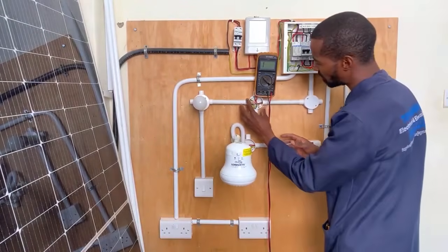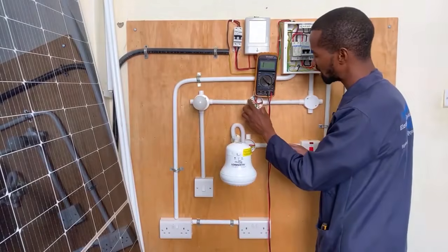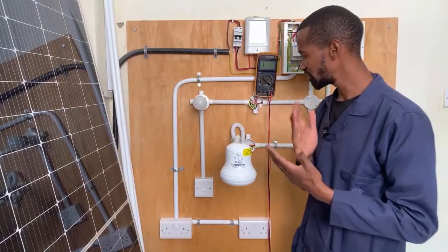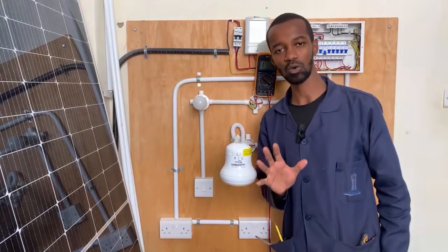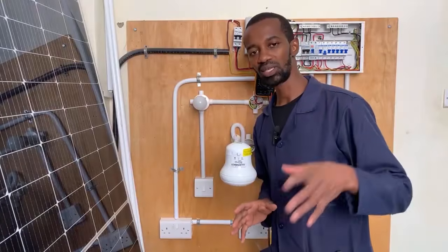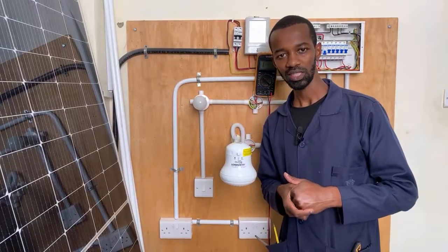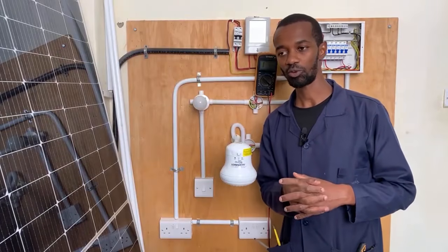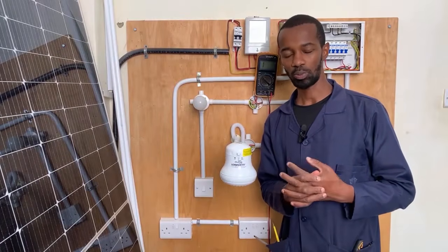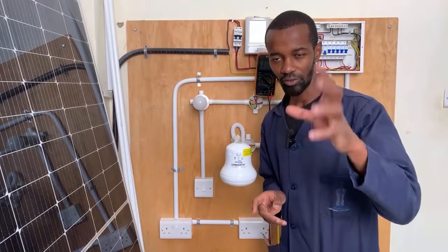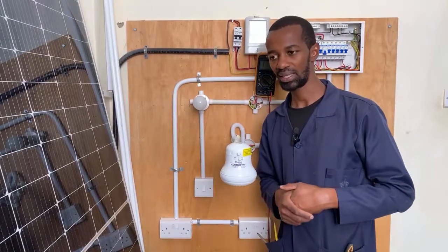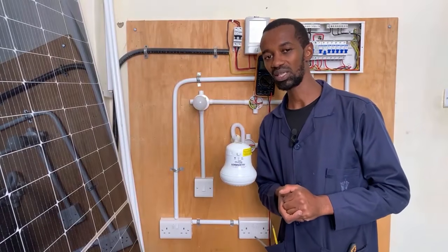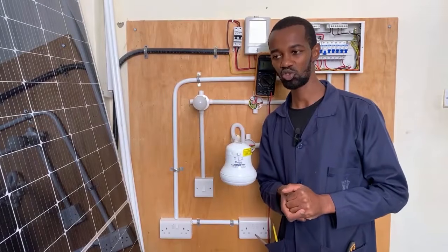For us, we had a makeshift problem at this point here. But how will you arrive at this point? You go on isolating every circuit. For instance, say there was a lighting problem in the sitting room. Or probably the security lights were not powering on. These security lights probably have 4 switches, I'm just assuming, or they are served from a photo cell. So all of them are not powering on. You narrow down to the photo cell, or you can take individual lights and start powering them on, but that will be tedious. Simply isolate the whole circuit from where the MCB has tripped.